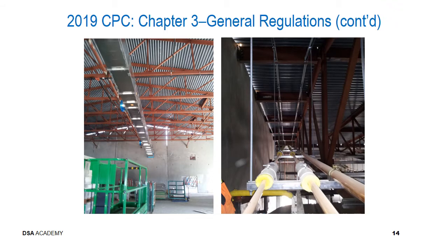The thing for a project inspector to consider is this is how the partial installation is going to look. And this particular installation is appropriate to keep the pipe from moving during the water pressure test.